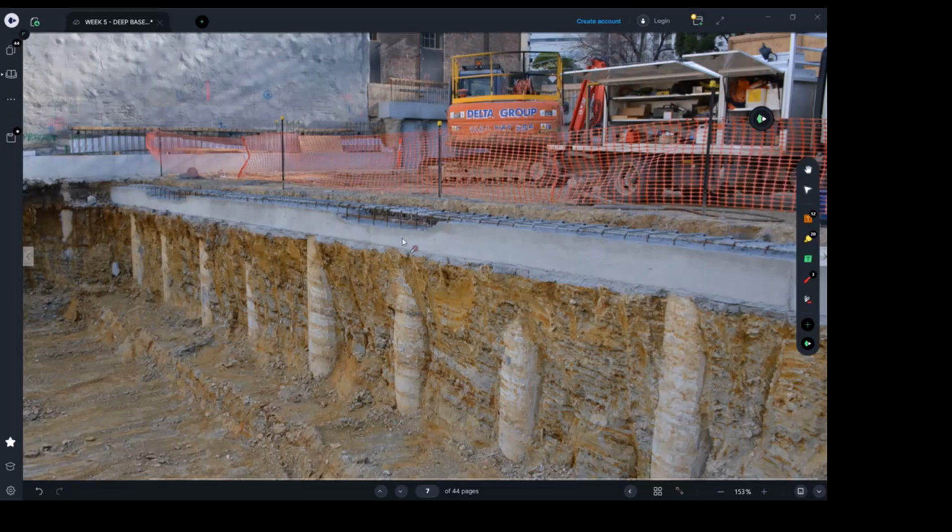At this stage, what I want you to know is that in day one, we don't excavate the basement. We just excavate the holes. We build the concrete, whether by using the CFA method or another method. If we use the CFA method, we will excavate, pour the grade concrete, submerge the reinforcement. Then the reinforcement needs to be lapping with the pile cap. Then we're going to build the pile cap. Then when the concrete gets hard for the pile cap, we start excavating here.